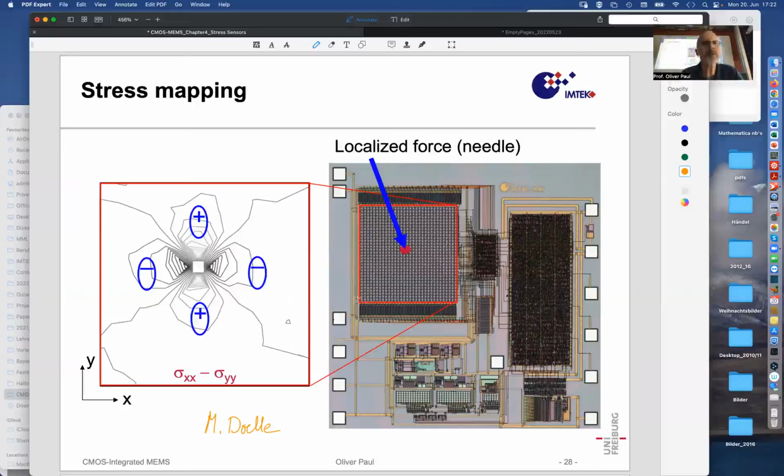Each one of these little pixels is a sensor with 4 contacts and a gate on top. And then, of course, there needs to be some multiplexing structure, and then some digitization structure, and so this was all built in here based on circuit blocks that were available with the company.